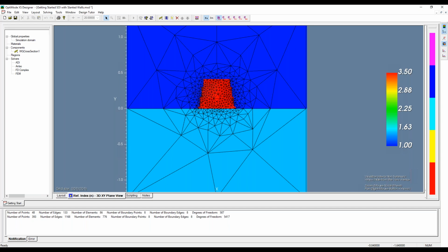In our OptiTools software, or utility that comes with it, we have an overlap integral. So you could choose some excitation field and then overlap with the modes of a waveguide that you've exported. So you could find out how the excitation takes place that way.